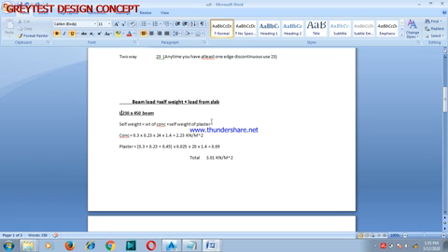So you can see the calculation is very simple. Plaster, concrete, self weight. For your plaster, 0.3 is the bottom depth of that beam, and then the width of the beam, the density of the concrete times the factor of safety. The bottom depth of that beam, the width of the beam, and then the overall depth of that beam is 450.